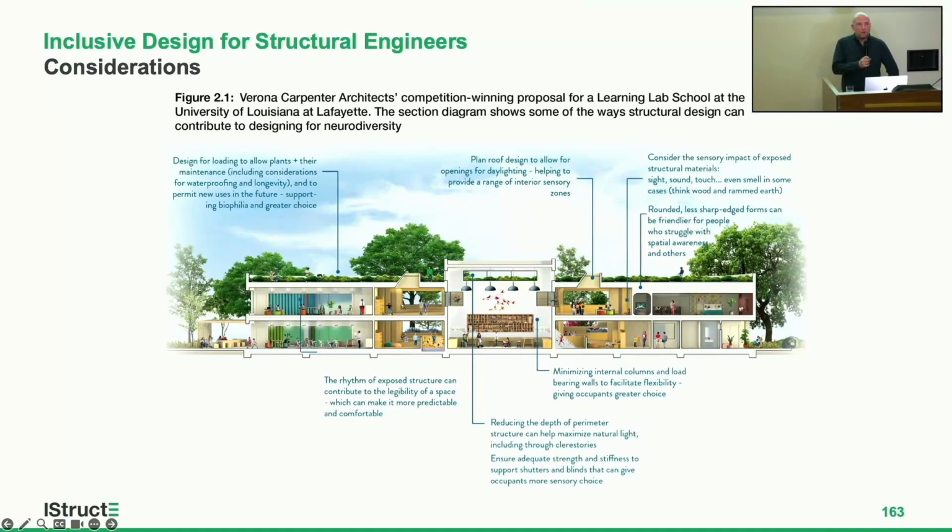I designed a few commercial buildings in London where it was all about lining the window mullions with the column, with the ceiling grid. The reason for that was that that space could be subdivided in lots of different ways to suit lots of different tenants. So it's not about creating big open plan spaces, but it's putting in place a structural grid that is well considered and allows flexibility in the future.